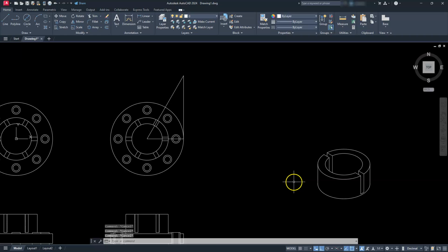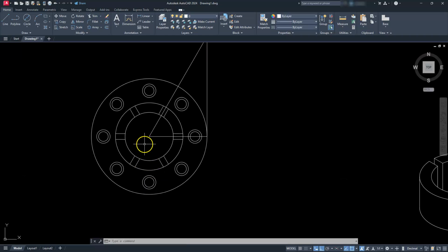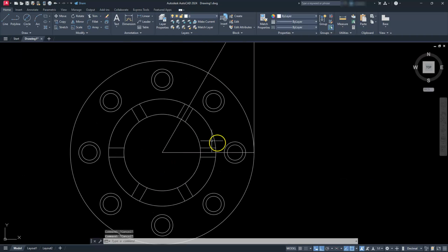It's kind of good to write those numbers down sometimes. And what I'm going to do next, now that I have that number there, and I think I went out too far. No wonder that line is so big. Give me 1 second here. It's the wrong length. Let me go ahead and put that line actually to this endpoint. There we go. And then let's use the fillet command on that one.